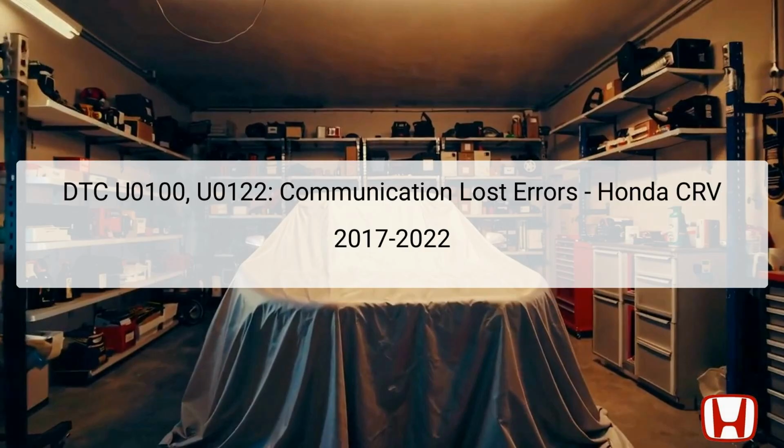Specifically, DTC U0100 refers to the power control unit losing communication with the powertrain control module, PCM, while DTC U0122 indicates that the power control unit has lost communication with the anti-lock braking system, ABS, and vehicle stability assist, VSA modulator control unit. Understanding these codes is critical for diagnosing and resolving communication failures effectively.